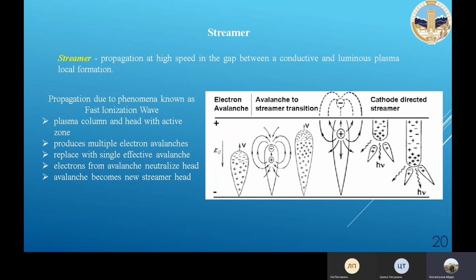As the avalanche lengthens and the number of carriers increases, the charge near the front of the developing avalanche increases. The electric field strength also increases more and more, and at a certain intensity this charge may propagate, partly without the participation of electrodes, due to the high tension. This is called the avalanche-streamer transition: the transition of discharge from the multi-avalanche form to the streamer form.